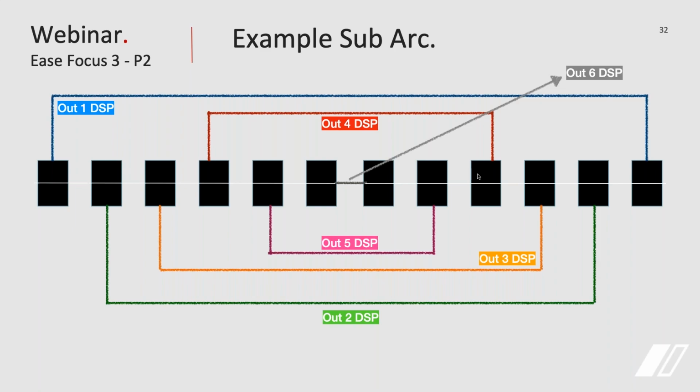Now, for our purpose, for DOS.NET and AERO 20s and AERO 40s, we have DSPs built into every box. Once we connect into DOS.NET with our processor and all of our units in Cat6, and we have control of every single subwoofer, we can now build digital groups of these in DOS.NET to organize ourselves and then link the delay channels between them.